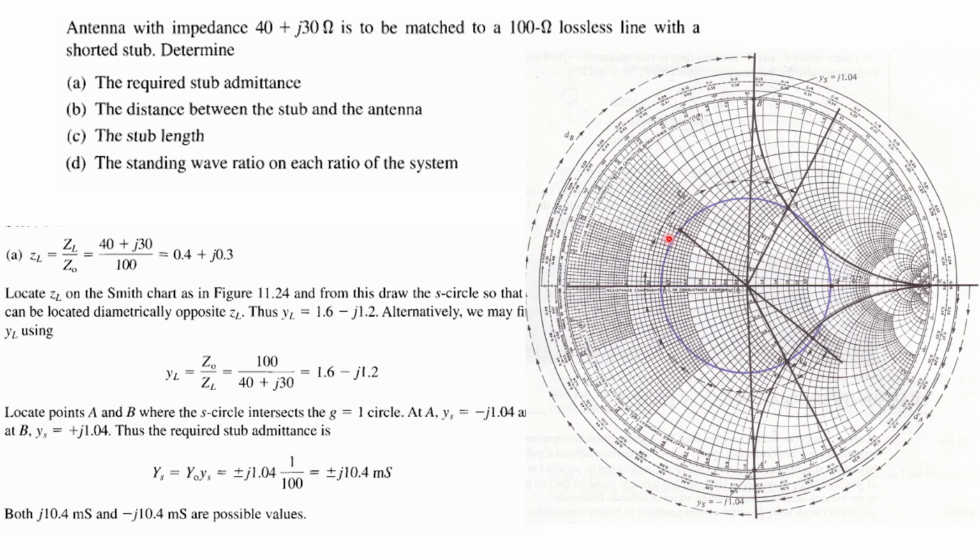Now what to do? Find the origin. First we found the location of ZL, the point we have already got. Now, where is the origin? Always remember the origin is at 1 comma 0. So this is your origin. Now connect your ZL point to the origin and extend it. Also, taking the distance from the origin to ZL as a radius, draw a circle like this. Once you draw the circle, this is called the S circle.